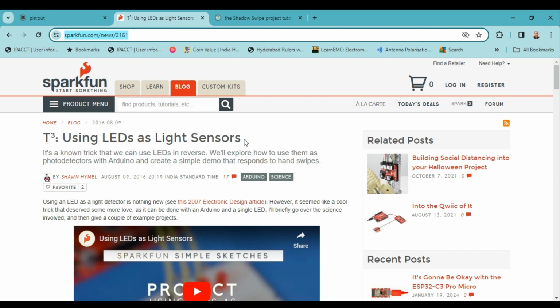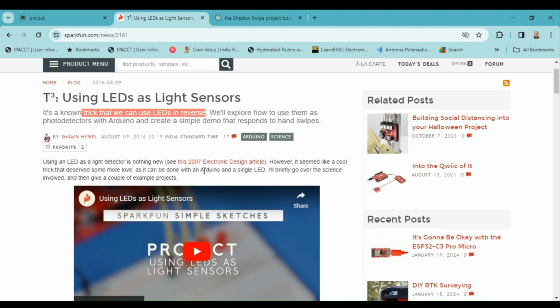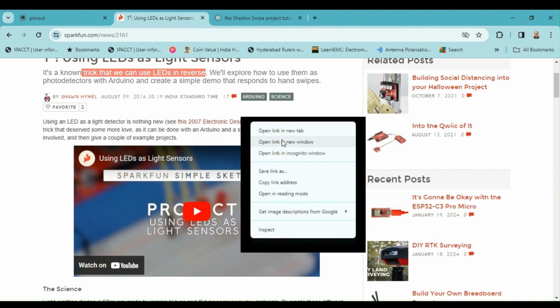This method utilizes the parasitic capacitance between the anode and cathode of the LED. When an LED is reverse biased, the parasitic capacitance charges to the voltage applied between the anode and cathode. It is feasible to drive both LED terminals using two microcontroller I/O port pins. Feel free to read through the document at your convenience to learn more. I have also included the reference article link. In simple terms, the section Measuring the Light explains how this works.